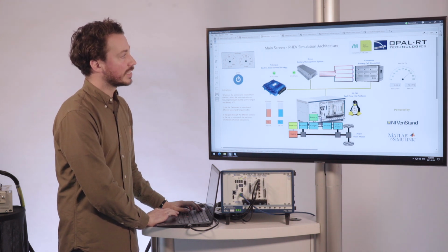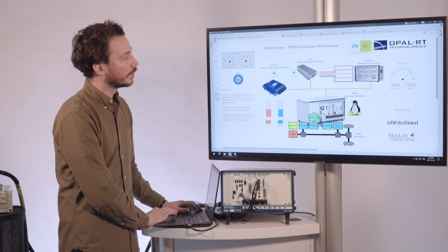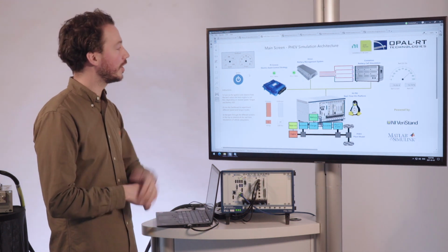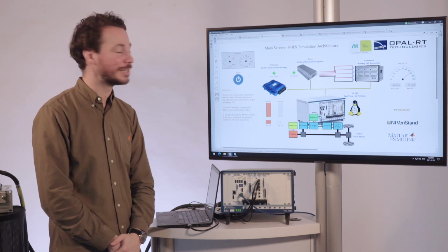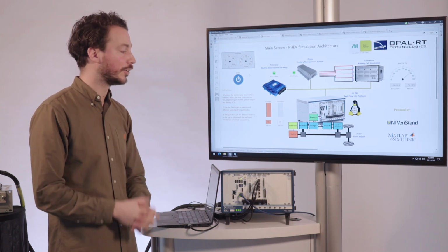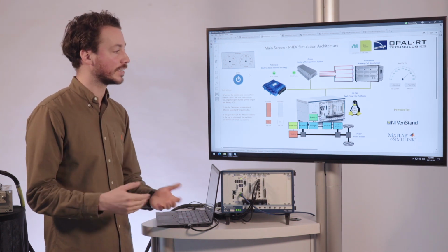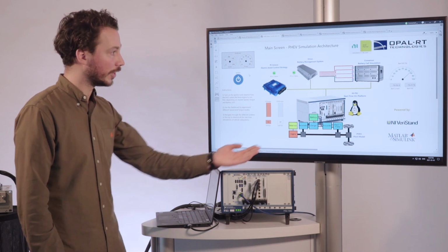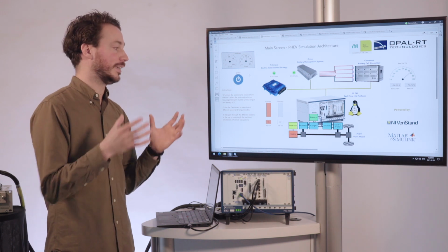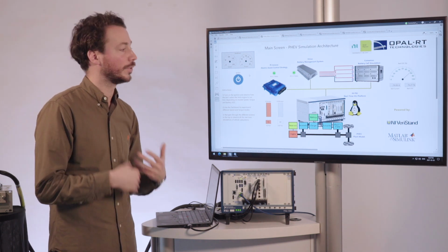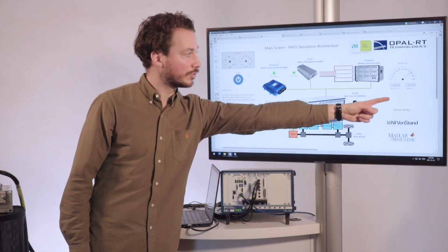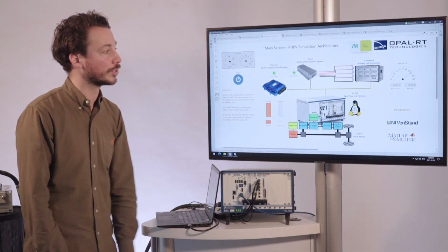Now in cases where we're going simply too fast, okay, such as here, we can see, let's say this is in kilometers per hour, not miles an hour, okay, which is still got to stay within the speed limit. Now we have the full combustion engine producing the output. There's zero output from the electric machine. As we can see here, we actually have a negative battery current, which means that the combustion engine is producing power with the generator, that it's actually charging the battery. So we can see here that the battery state of charge is going up, okay, by 0.01%.